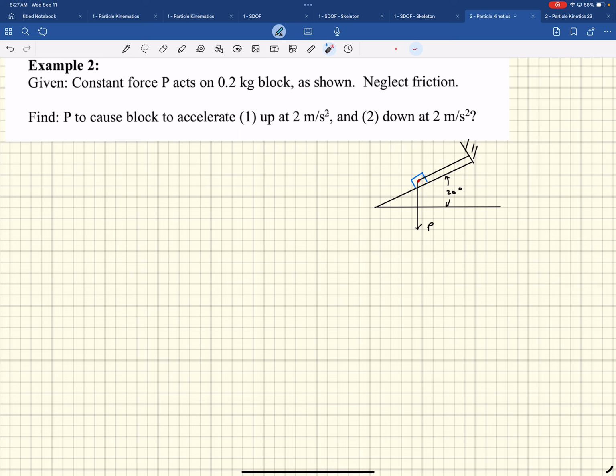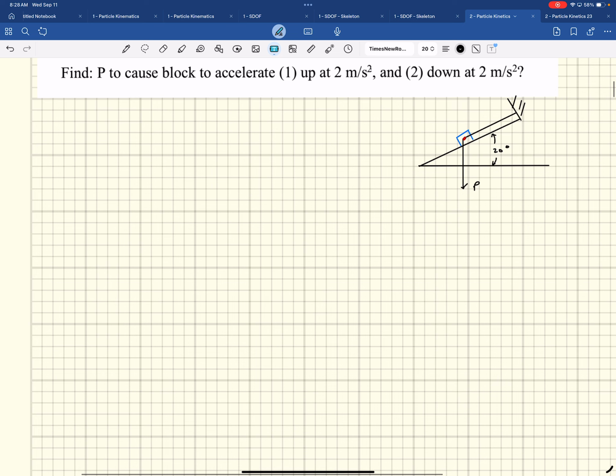Obviously, look at it and apply some intuition: what's happening, is it going to slide up or slide down if I pull the thing? Sure, do that. But when it comes to solving it, just go right back to that procedure. Free body diagram, equations of motion, kinematics, it's solved. It'll lead you there every time. That's what's beautiful about this part. Okay, step 1, free body diagram.